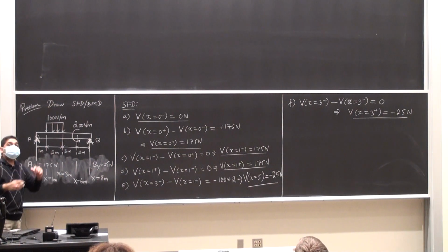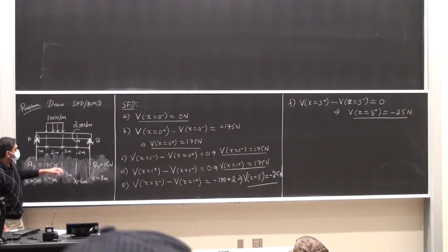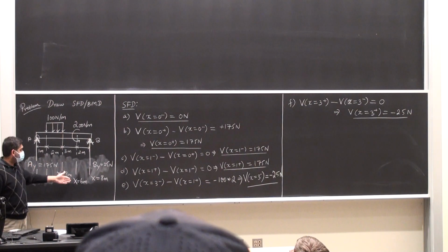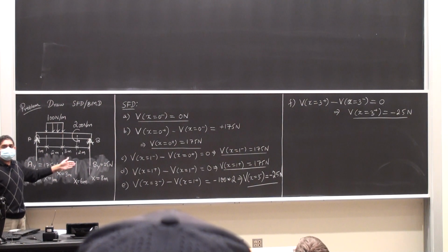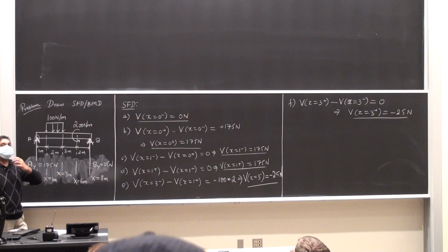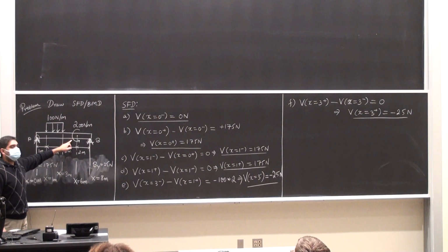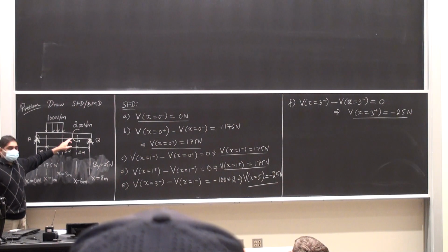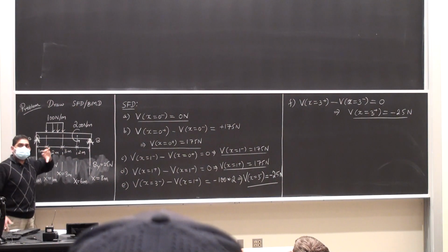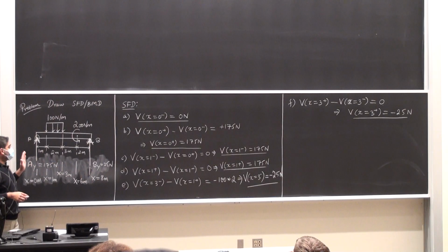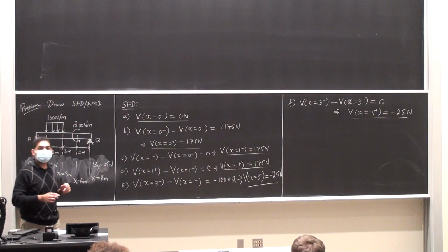Now you've got to start thinking smart. What's my next stop? My next stop is x equal to 6 minus and 6 plus. Right? That's my next stop. But we looked at the derivations last time and we figured out that this coupled moment does not do anything for my shear force diagram. Which means I can kind of ignore its presence. There's the gorilla in the room, but you can ignore its presence for the time being, and completely zoom past and go to 8 minus.